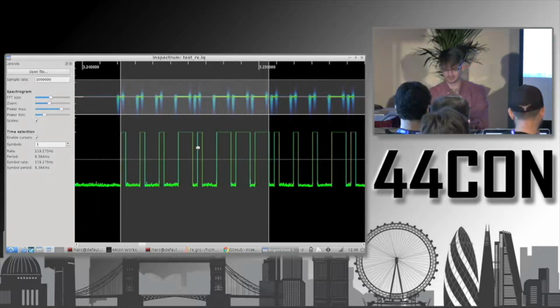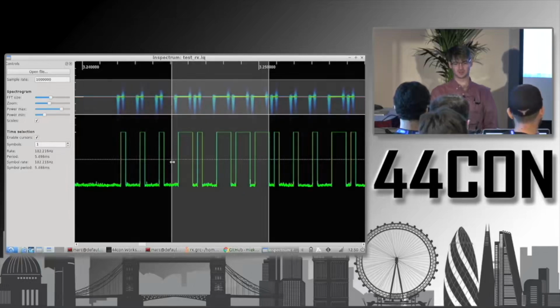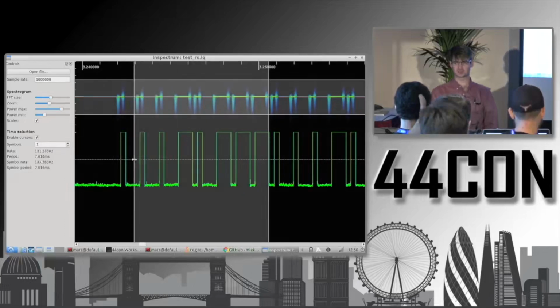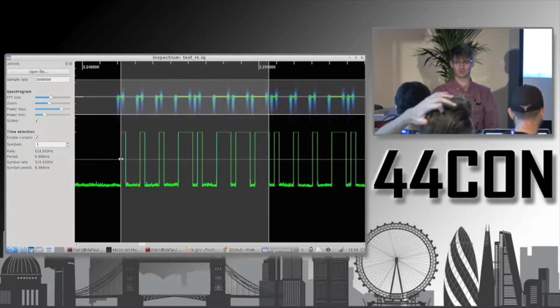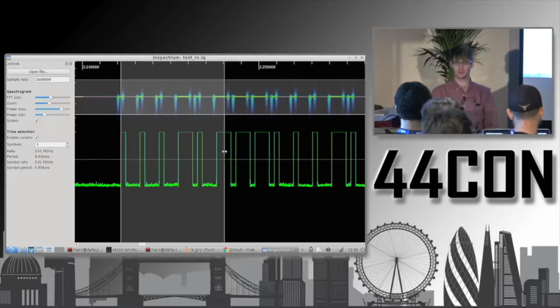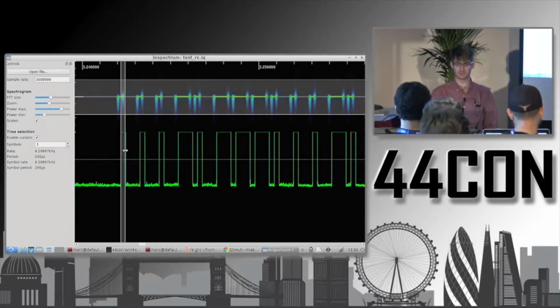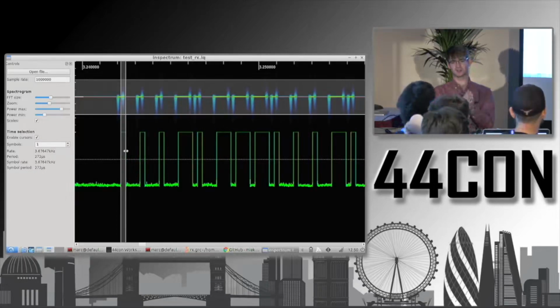I've become a big fan of it. So back to cursors. Basically, click on the cursors button. Drag the leftmost vertical bar over to the rising edge of our signal here, and then you drag the rightmost cursor over to the falling edge there.